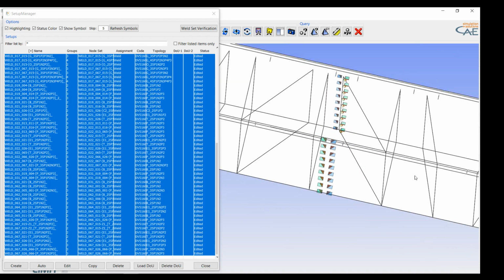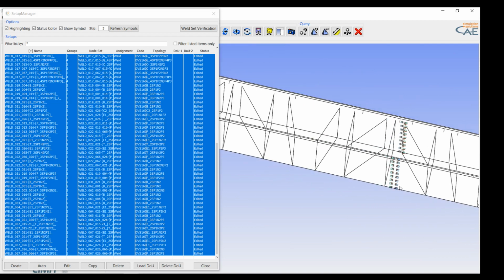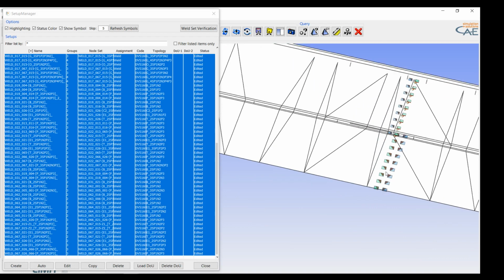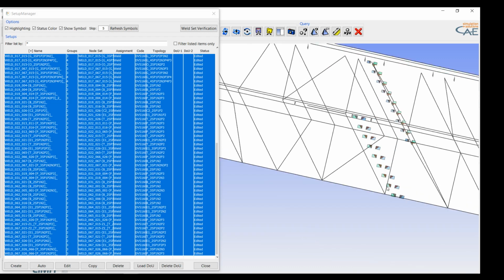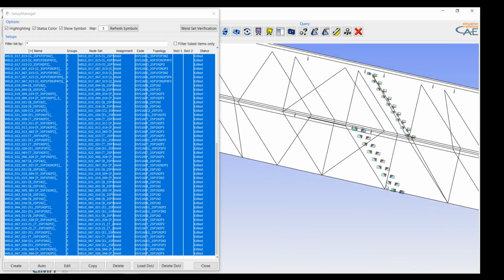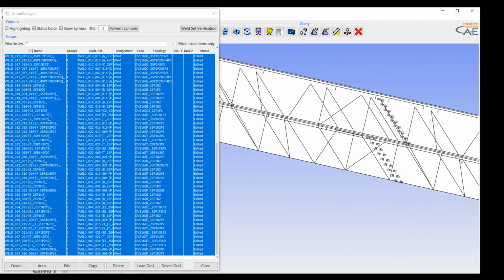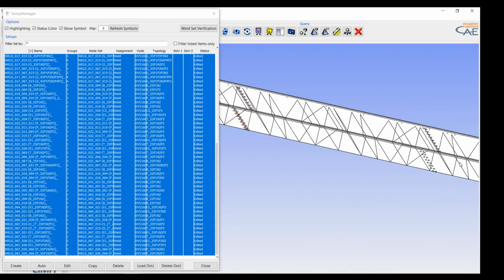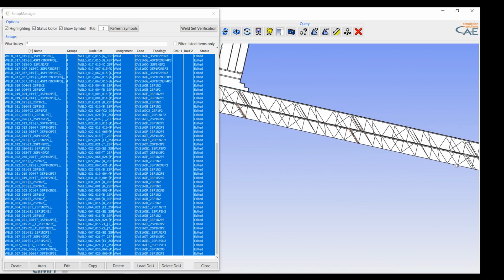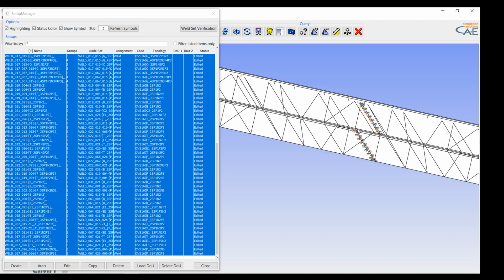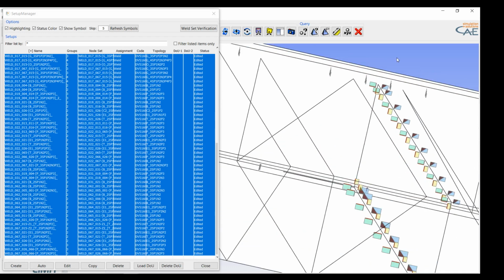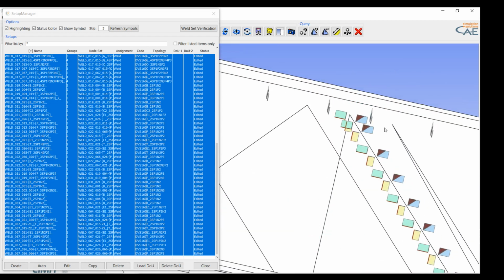Here, for example, this butt weld seems to be welded from the wrong direction, but for the first approach we had this thick check, butt welds welded from both sides, so we are fine. Here you can see the typical profile weld. We have the attached component, and here we have a horizontal and a vertical element for the profile.